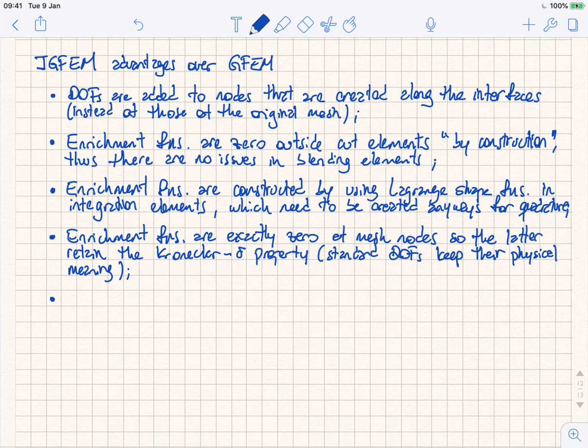No, not exactly. I thought that was the reason for having enriched FEM. That if the node is on that place, it cannot handle it well, and you don't know where the peak lays. No. What you want to see is that whenever your discontinuity is going through the element, then that element cannot reproduce the behavior, right? If you have different material properties at either side of the discontinuity, this non-conformity prevents you from capturing the physics, okay? That's where we have to enrich.